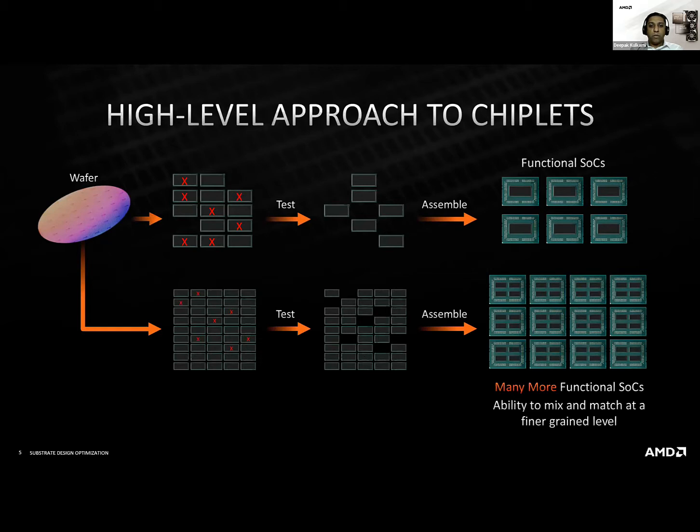When these chiplets are manufactured through the wafer processing step, they result in a higher number of yielding units that meet the customer's compute demands. So the first point I wanted to highlight is that chiplet architecture provides a yield benefit and a method for resolving some of the reticle limits that would have limited the number of transistors you could pack in a particular device.